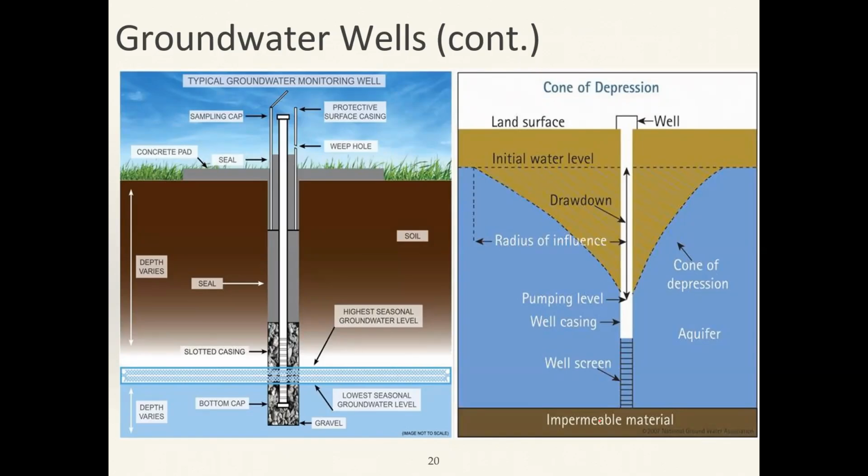Because the pollutants are filtered when the water infiltrates through the soil layers, through the unsaturated layer. But if you drill a well, then you are making a connection from the ground surface to the groundwater aquifer, so that surface water pollutants can easily enter into the groundwater aquifer. Therefore, when you drill a well, it is very important for you to seal it like this.